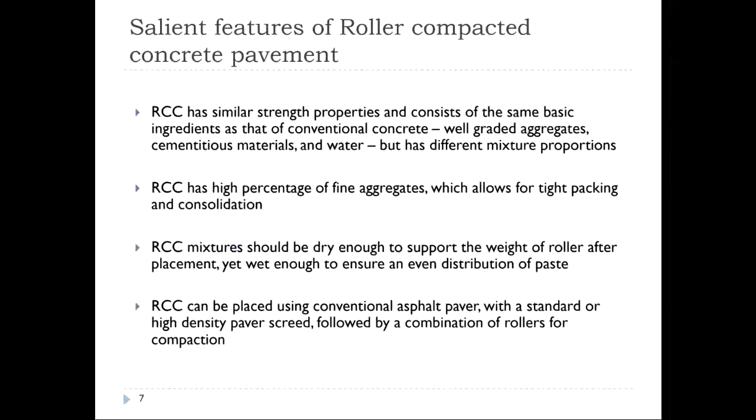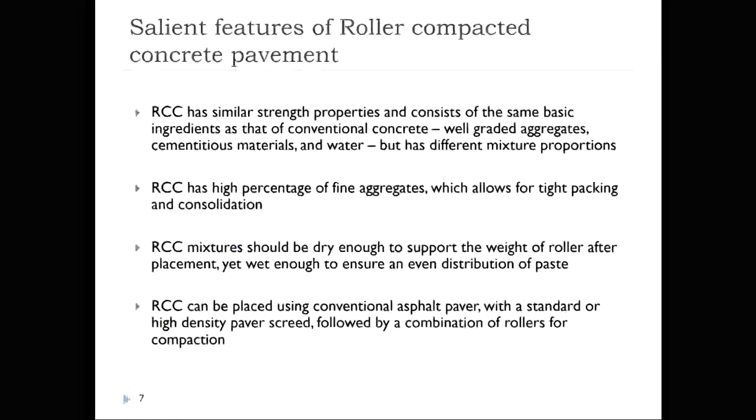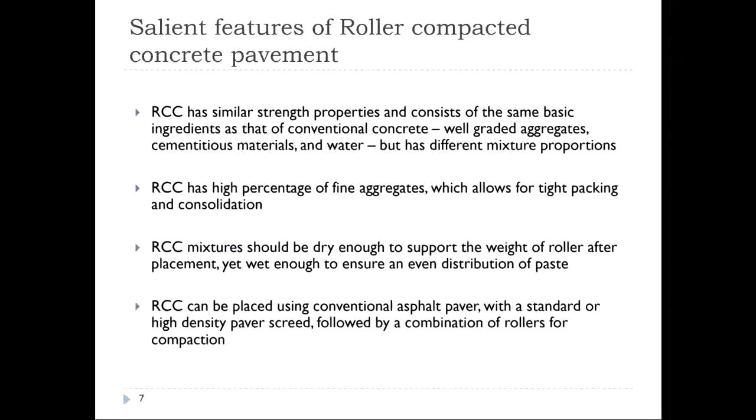capability of these mixes. Now, when it comes to the water content, roller compacted concrete pavements should have enough water so as to provide an even distribution of paste, but that water content should not be more. If the water content is more, you will have what is known as sinking of the rollers in these mixes.